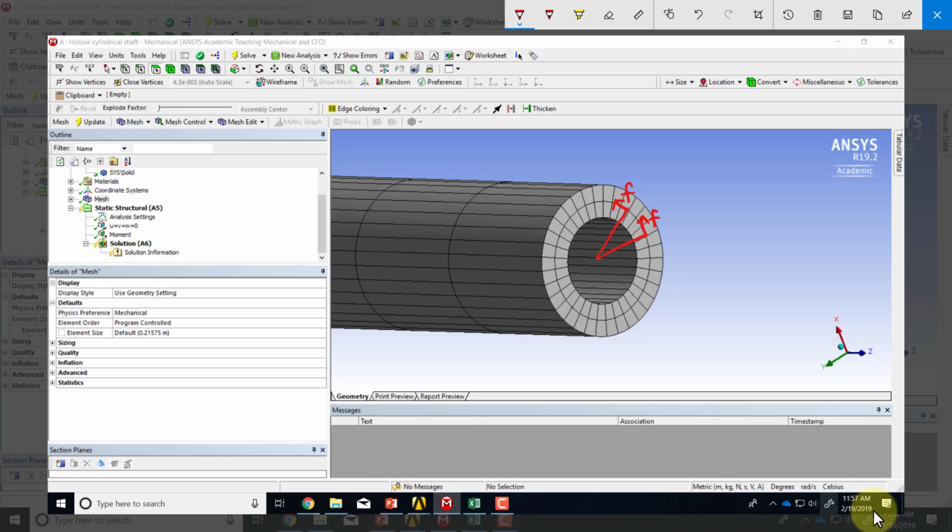And essentially what that is doing is, if you think in terms of the boundary conditions on the boundary value problem, that's setting the normal stress to 0 underneath the hood. So you're specifying sigma ZZ equal to 0. Z is out of the plane of this face. And sigma XZ, or ZX, is some specified value, and sigma YZ equal to some specified value. And this will vary along that cross section. So that's what you're doing.